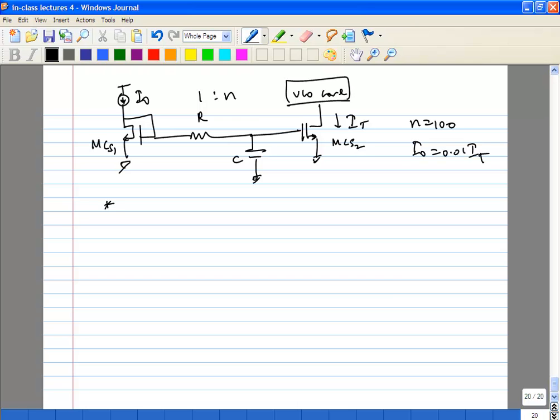What kind of RC values do you think you need to get rid of flicker noise? You obviously can't get rid of all flicker noise, but you have a certain corner up to which you can take care of it. That's typically decided by the in-band of the VCO, which is going to matter less because your PLL is going to reject the close-in noise of the VCO. Once you put it in the loop, the PLL rejects the close-in noise, but you still have a certain spec because it will be additive.